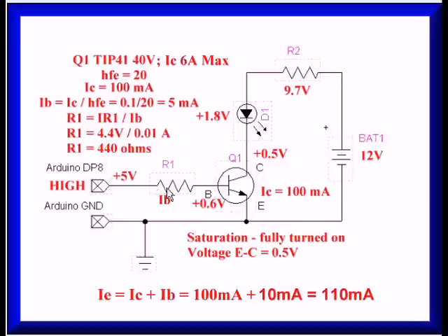That really should be the voltage. What is my voltage across R1? We got 5 volts here. Let's look at this. You notice I got 0.6 volts here. When I do these calculations, I always use 0.6. So I have 0.6 volts on the base. That means I have 4.4 volts left on the resistor. I have to drop 4.4 volts with the resistor, and I have to supply at least 5 milliamps.